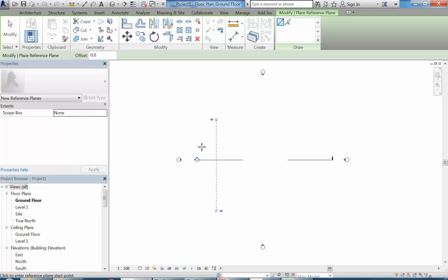face of your walls. So I've got a vertical reference plane, and I'm going to also draw then a horizontal reference plane, which is going to represent the inside face of my, well, I was going to say my north wall, but it's actually going to be the south wall. North will be facing down this way. So then I'm going to draw another reference plane over here, using the next critical dimension, which is, or that dimension I just showed you, 10.9 metres, so 10,900.